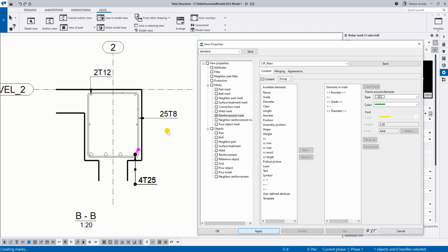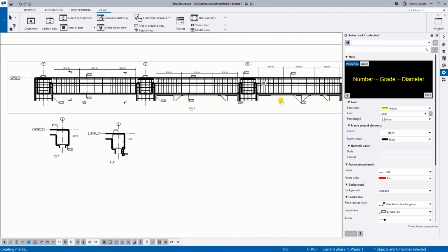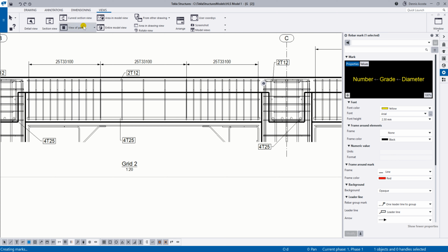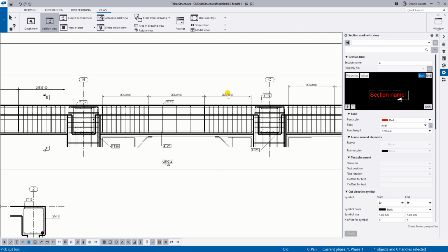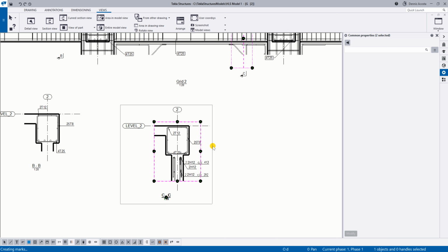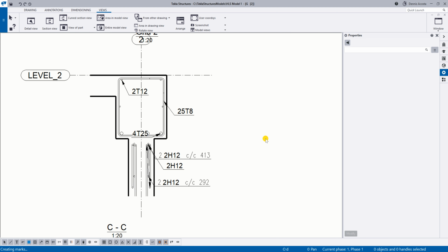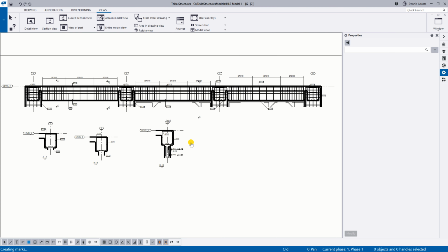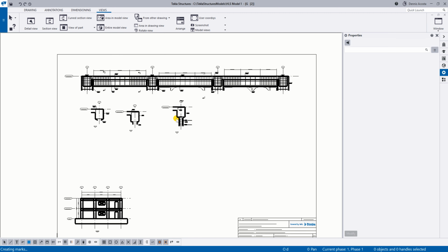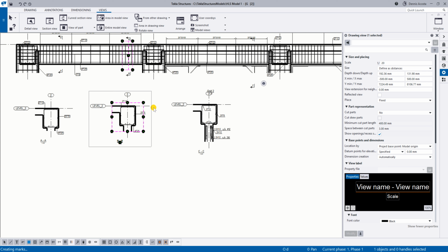So meaning, when you create another view, let's say I have another view here, section view, including the wall. See? Here, there is more information. Okay? So again, that one is for the beam. You can put the section and then you can have as many sections as you like so that it will be more detailed, much easier for the fabricator or the erector to use.